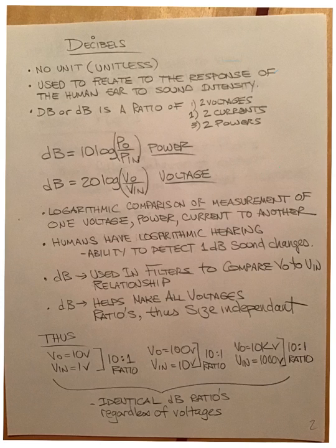We'll be talking about voltage. So you can pack this equation away because we generally won't be using it. We will be using the voltage version of it. It shows that the dB is a voltage ratio of what the filter provides on the output versus what you sent in. And the complete formula is 20 times log of V out over V in.